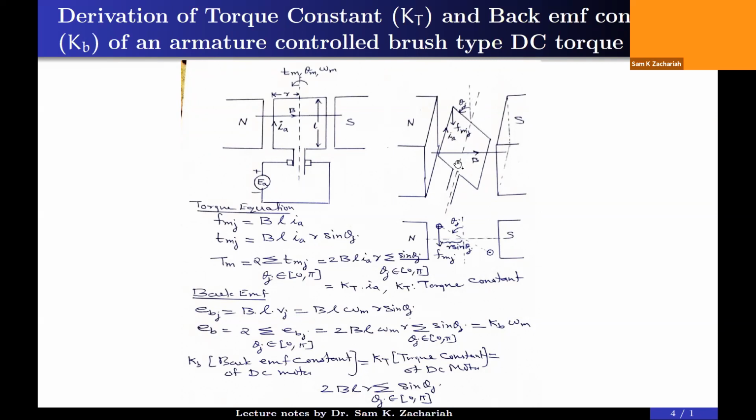This dotted line shows the axis of the rotating element, or axis of the motor. While this coil is rotating, if you give a firm connection from the voltage source to the coil, what will happen? That will get twisted. That is not possible. That is why a sliding contact is provided from the voltage source to the coil, and this is called a brush.